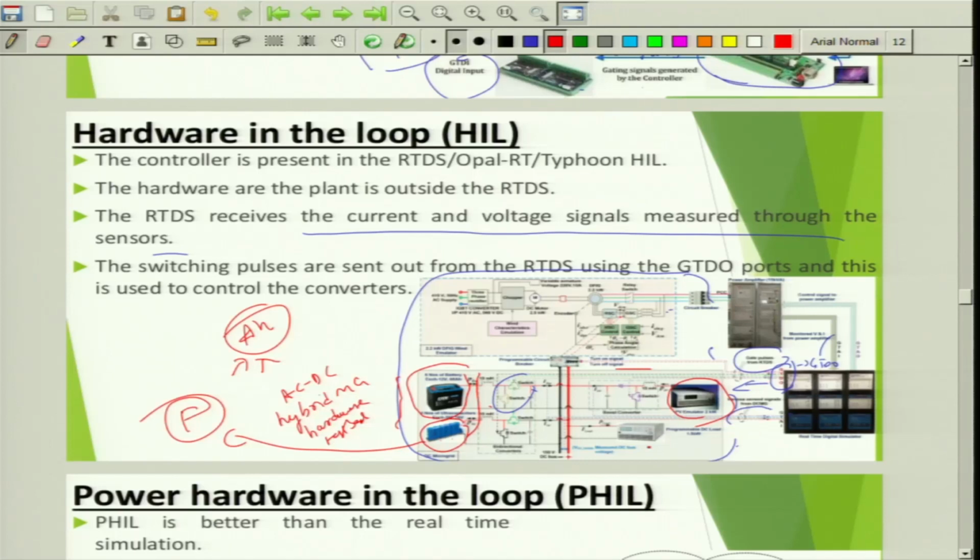So you can emulate these characteristics using the PV emulator, and we also have a programmable DC load. This is a programmable PV emulator and programmable DC load. That means you can emulate the characteristics of 3 varieties of loads basically. Zip load we call it. Zip means constant impedance, constant current and constant power.